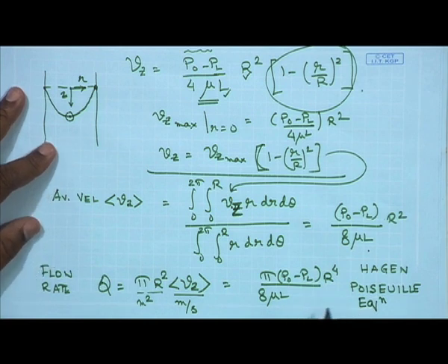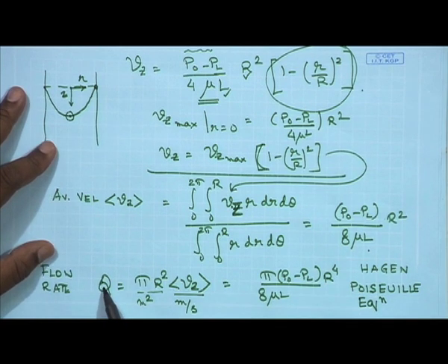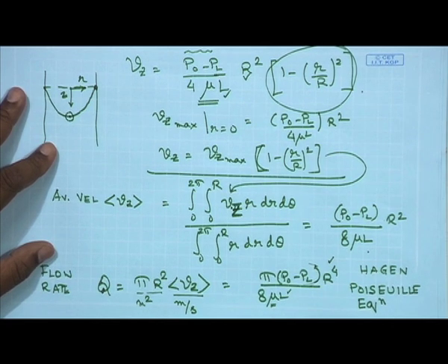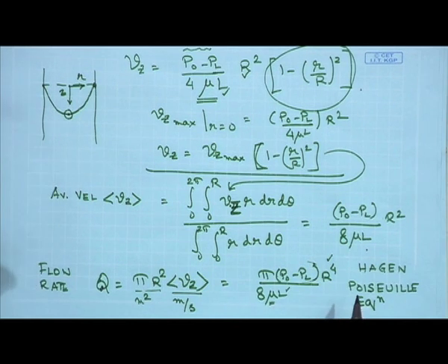So this Hagen-Poiseuille equation gives you the volumetric flow rate for a fluid which is flowing through a vertical tube because of the presence of a pressure gradient and body force. So this is the imposed condition, these two are the geometry, and this is the thermophysical property or transport property. So now you can clearly see how we explain the principle of the capillary